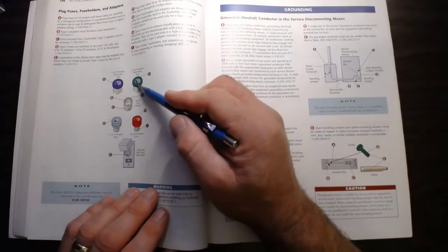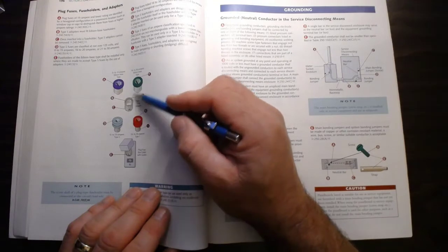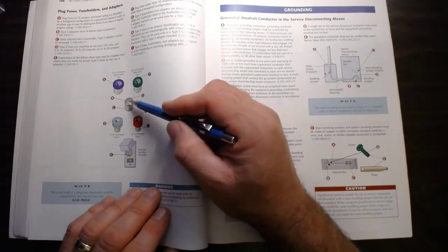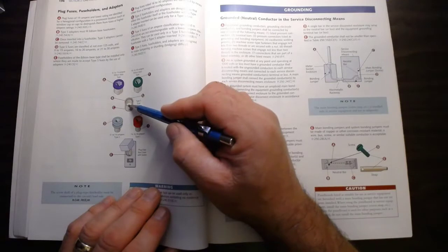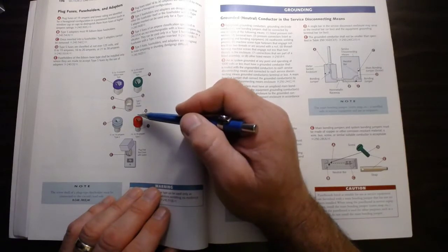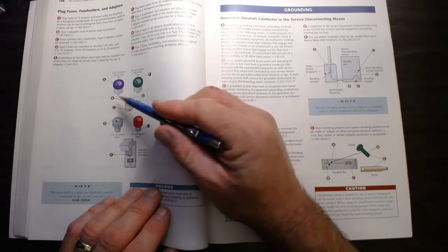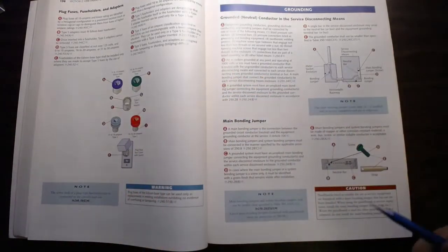Also, when you're looking at these, sometimes they took a penny and put a penny in the bottom of the base and screwed the fuse back in, and it effectively bypassed the fuse and made it non-fused. So that was a safety issue. And you could probably even unscrew them and find those pennies in there as an example that the fuses aren't working.